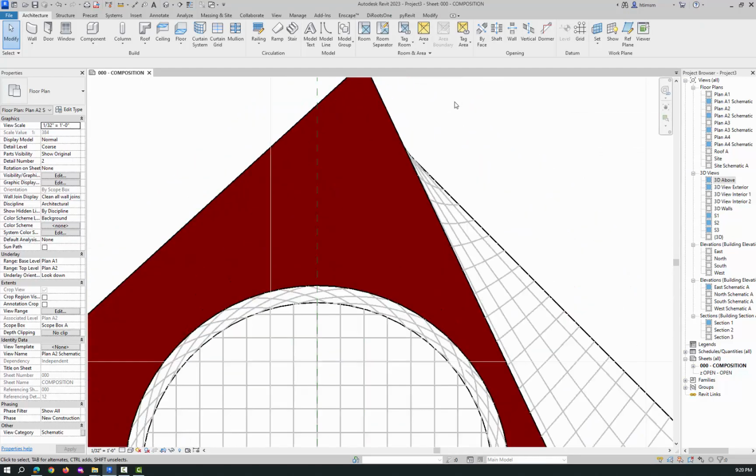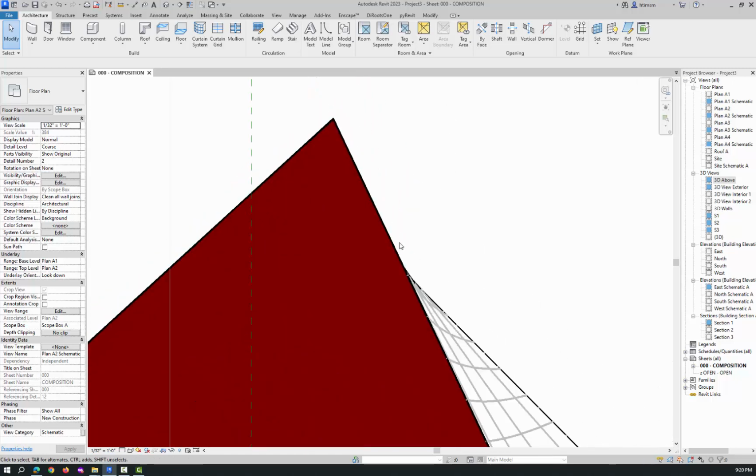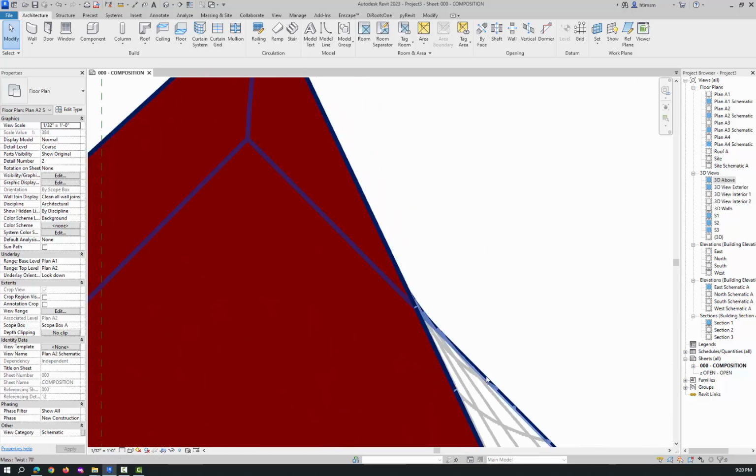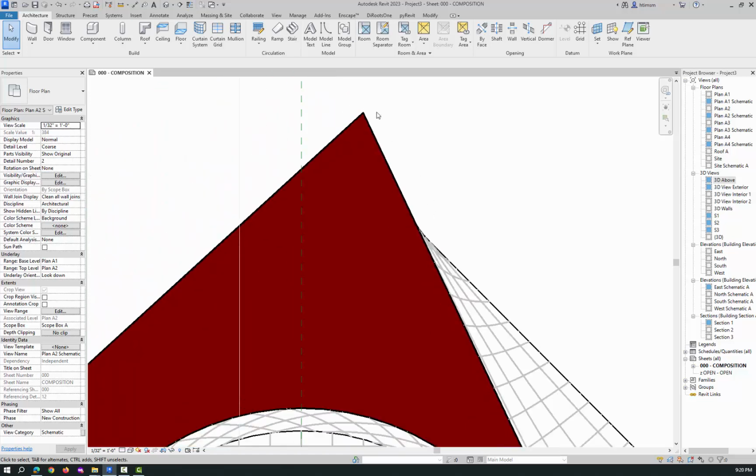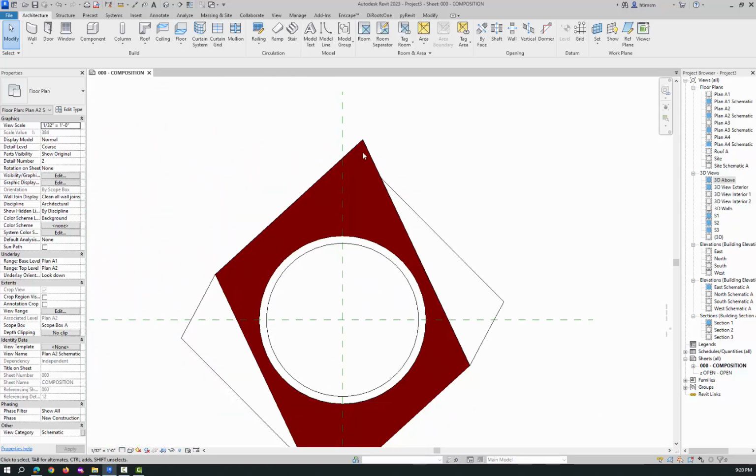There is a command that will show you line weight, so you can see the elevation line here, right? And the section cut line. And there is a difference. If you type TL, it turns the line weight on and off, so you can see what the line thickness is and what it isn't. So I want this section cut line to be much darker.